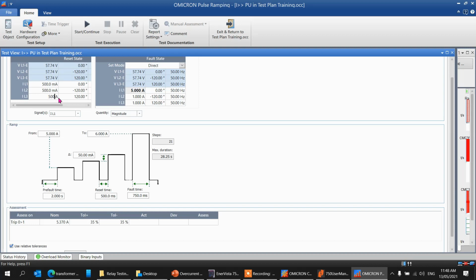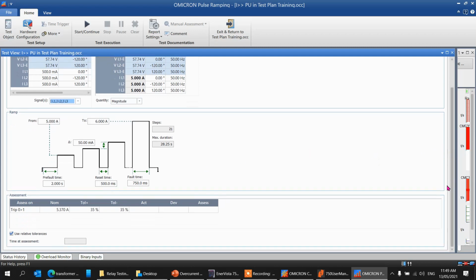I think in the signal there should be 3 phase. So this one should be 3 phase, because if you only put one there, it means it will trip the ground. So your expected feed from the relay should be from open to close, which is a dry contact. Open to close.